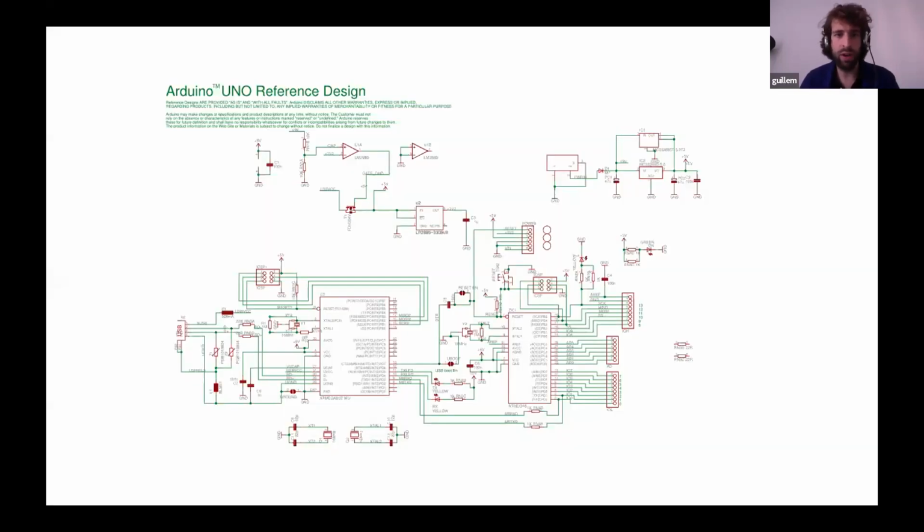The kind of bootloaders we'll talk about today usually are small pieces of code that live inside our Arduino. And by Arduino here, let's think of an ESP32, a NodeMCU, an Arduino Uno, that sit on our microcontroller and that allow us to put code into our microcontroller in a convenient way. So when a device doesn't have a bootloader inside, what usually happens is that we need something called a programmer. A programmer usually is a specific dedicated piece of hardware, like the ones that you build, to actually get code from your laptop and then put it inside one of these microcontrollers.